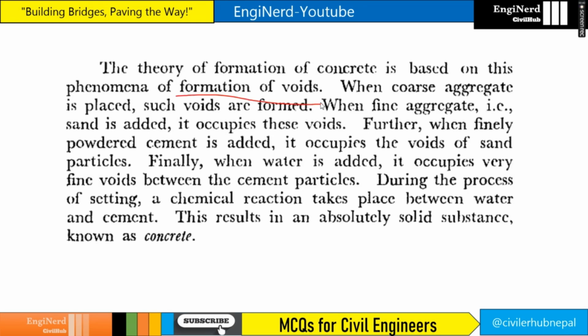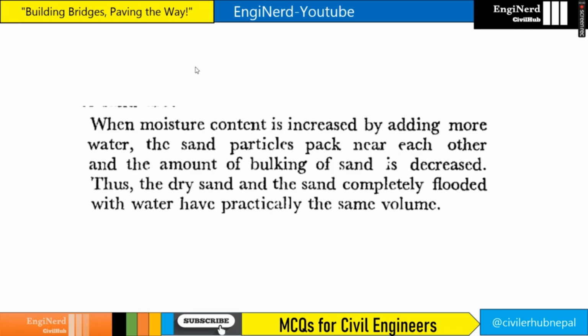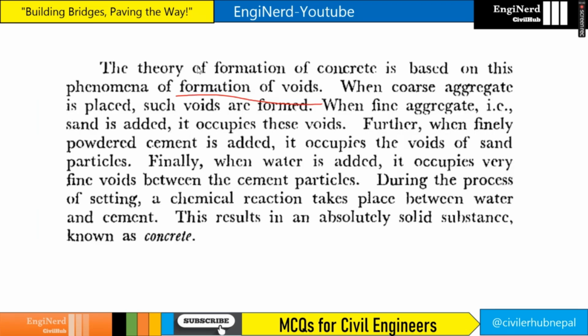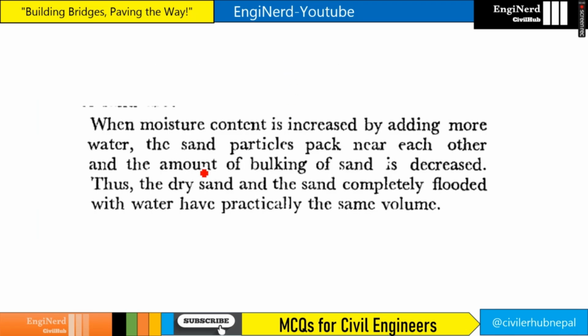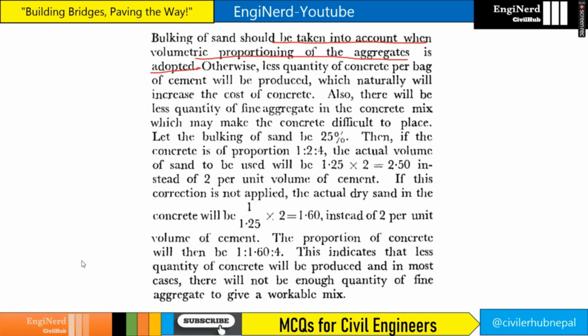For the second one, the question is whether the bulking of sand is taken into account, right? We see here bulking of sand should be taken into account when volumetric proportioning of the aggregate is adopted. And for the third one, the dry sand and the sand completely flooded with water have practically the same volume, right? So all three are correct. So our answer will be all of the above.